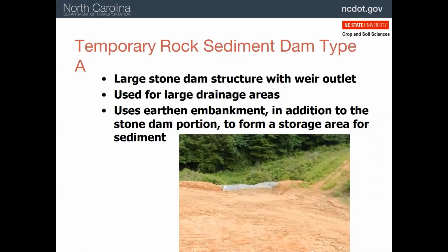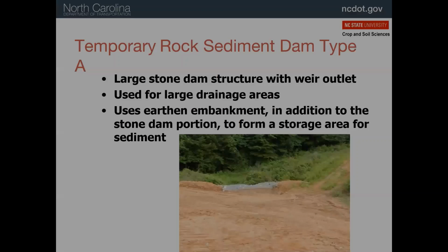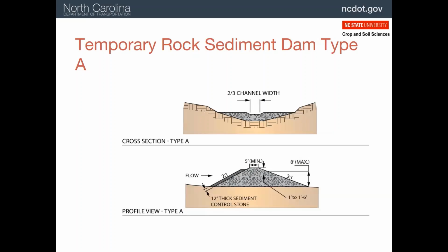Now, basins sometimes are the old type with the rock and the stone as an outlet. And here's the front and cutaway views. You can see some of the details where we have the large rock, a weir cut in it, and then the face of 57 stone washed gravel, at least a foot thick. So what does that do? You should know by now it slows the flow through the rock and pools the water.